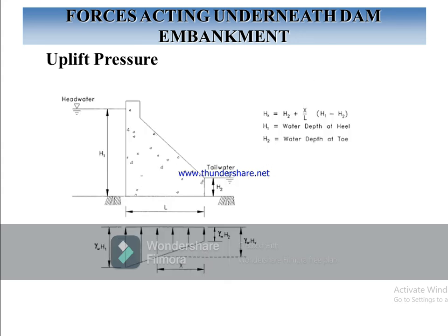So we come to the diagrams for better understanding. We put two diagrams for better understanding. First of all, this one. Here is the height h1, and how much it affects the uplift, which is really dangerous for the dam. For gravity dams and earth-filled dams, there is a lateral effect and an uplift effect. So to reduce the uplift effect, we use some mechanisms also, and this is how we calculate these pressures.